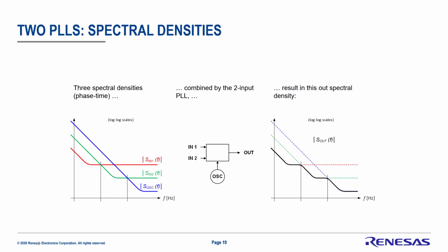In addition to looking at the filtering characteristics, an interesting aspect is the spectral densities or the phase noise that you can create by doing this type of technique of clock combining. If we took two input references, we can effectively not only combine the noise characteristics of the two inputs into the output, but even the phase spectral densities of the two inputs can be represented at the output. So effectively, you could take advantage of certain characteristics of each clock in terms of its short, medium, or long-term stability in order to generate your final clock output.